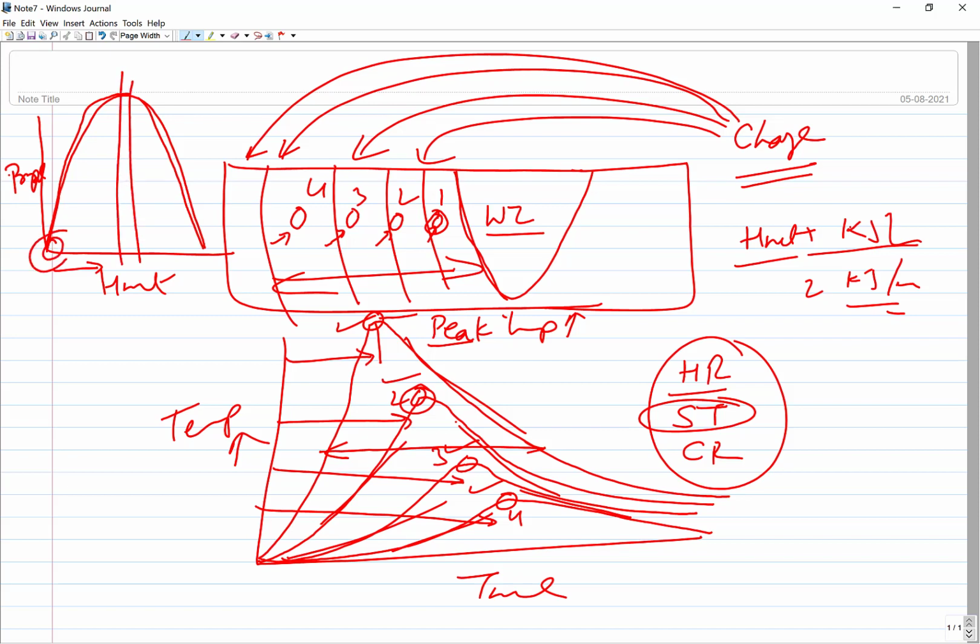When heat input is very low, you may find that the joint is not developed properly. There are a lot of pores because of the very high cooling rate, lack of fusion, lack of penetration, or lack of proper mixing in solid state joining, etc. So the discontinuities are there when the heat input is less, and when it is too high there is a coarsening of the structure, deterioration in mechanical properties, and deterioration in metallurgical properties, again compromising the joint properties. So there is a need for the optimum heat input. Even this is true for many solid state joining processes.